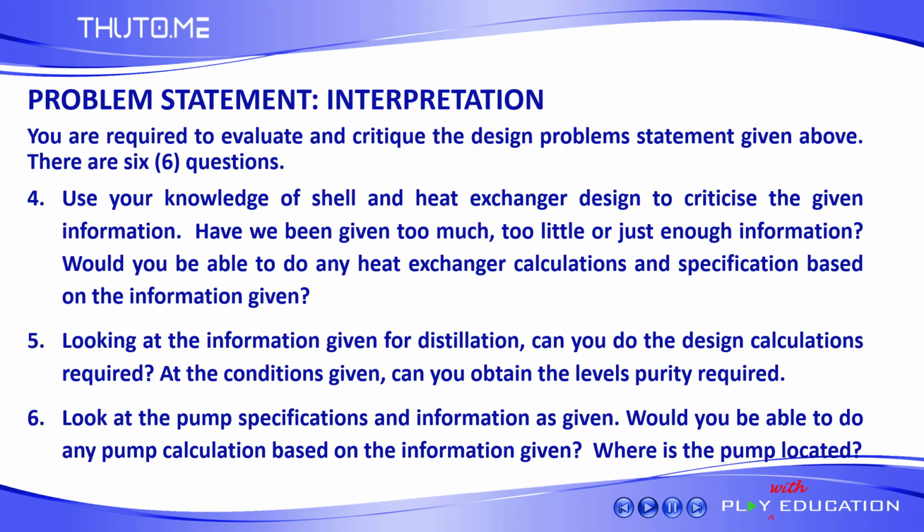In the 6th question, you need to look at the pump information given and answer the following. Can you do the pump sizing and specification calculations? Where is the pump located? Are there any height specifications or considerations? Can you do the NPSH calculations and check if the pump is positioned accordingly to prevent cavitation?